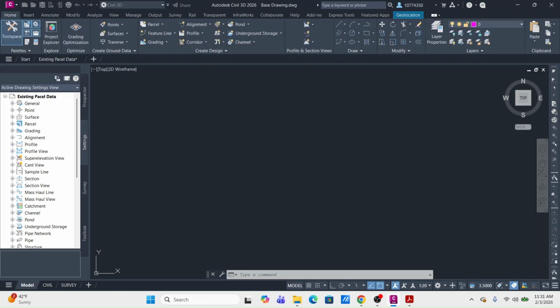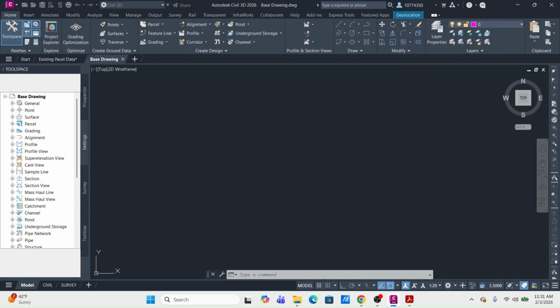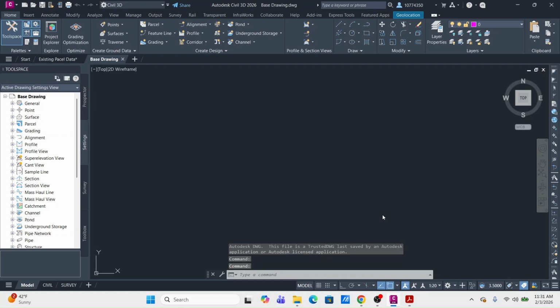And I just want to add real quick, I separate everything out into different drawings. I don't like compiling all of my line work, all my survey points, and everything into one DWG, because to me it's a lot of clutter and it's messy and I do not like it. I like to have everything separated out, and then I can do a command which is called XREF, where I can just start layering different drawings on top of each other, and I don't have to deal with all this clutter, and I can unload and reload things on top of each other. But I'll talk about that later. That's a later topic.